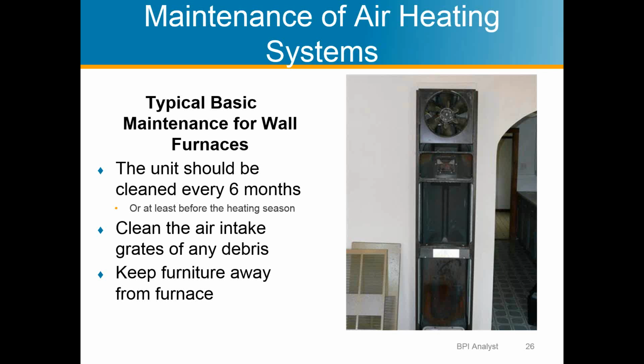So this is another type of gravity wall furnace where it's using a fan at the top. That's the fan right here. And this fan is just used to help circulate hot air in the house. So it's just drawing air up over the combustion chamber, which is this, up over and around that, and then blowing it out up here, or it could be set to operate just exactly opposite, where it sucks air in and blows it out down here. Typically it's the former, not the latter.